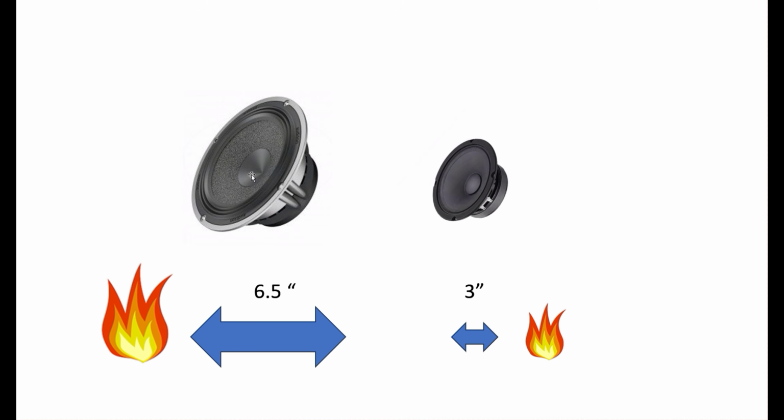So the same way as we have a high frequency limit, we have a speaker with a low frequency limit, and in the case of low notes, when you're looking at 100 hertz, then the 6.5 is going to win because it's got bigger cone area, bigger Xmax, and a bigger, stronger motor that can push more air and deal with more heat, right? So between the two, this is going to be the winner to play lower notes.